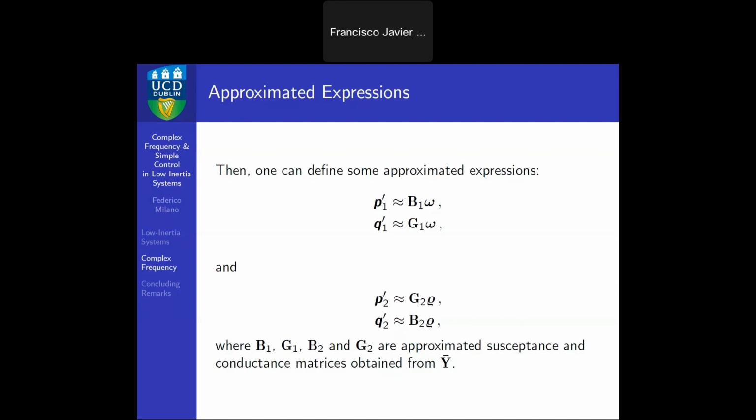And at that point, the only thing that remains are the losses. And at that point, you see that the only way is to change P2. You have only P2 in fact, and only the variation of the magnitudes of the voltage. So this is perfectly consistent. So in DC, it's just the same equations. It's just that you remove this one because there is no Q, and you remove these ones because there is no omega.